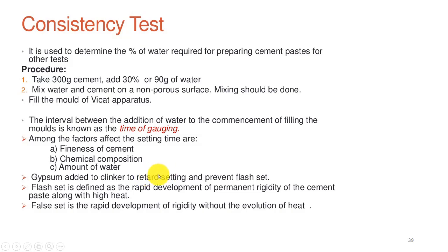If you see that the cement sample in the Vicat mold gets set just by adding the water, then it might have a flash set or a false set. Basically, these two sets are caused when the gypsum is added into the hot clinker; the clinker is not sufficiently allowed to cool down before the gypsum is added.